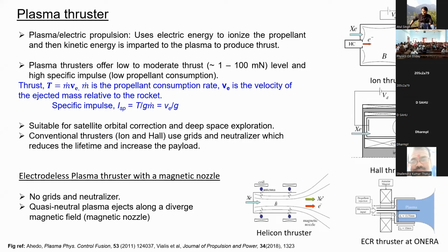So now what are the applications? Let me show what we are proposing, it is called the plasma thruster. So plasma thruster means ions are coming out from that system, the small compact system, ions are coming out, and ions are the ones actually taking the mass, right. So if mass comes out from the system, there will be a recoil too, right. If a bullet is fired from a gun, the bullet goes out, then the recoil comes. So that is what we call thrust generation.